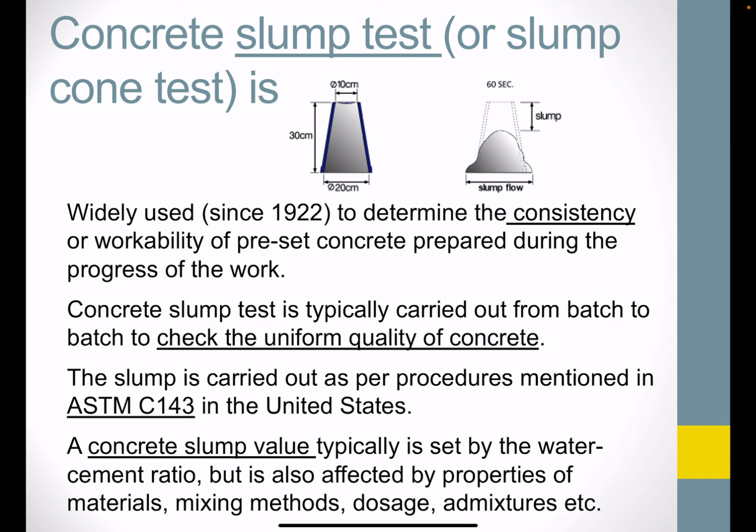So, as we consider how one assesses the quality of concrete at the setting or cure stage, we have various techniques, and one that will be focused on in Lab 2 is the slump test. The slump test involves shaping a known amount of concrete specimen in its flowing condition in a cone, and after removing the cone, allowing the material to settle or slump and measuring the displacement relative to the height of that shaping cone.